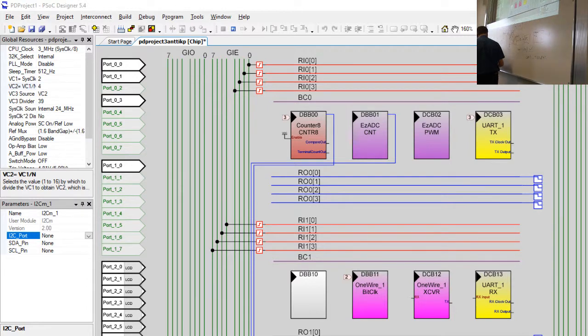That voltage here is 2 to the power of 12 millivolts. So a quite good conversion. So a 12-bit A to D converter and 2 to the power 12 millivolts voltage reference. So it means one bit here is exactly 1 millivolt.